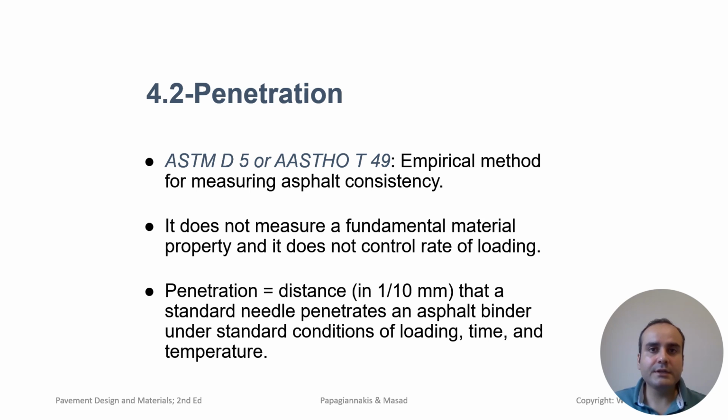The penetration test measures the hardness or softness of the asphalt binder by determining how far a standard needle penetrates the surface of the binder under controlled conditions of time, temperature, and load.